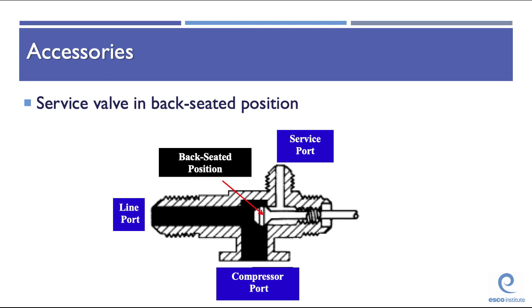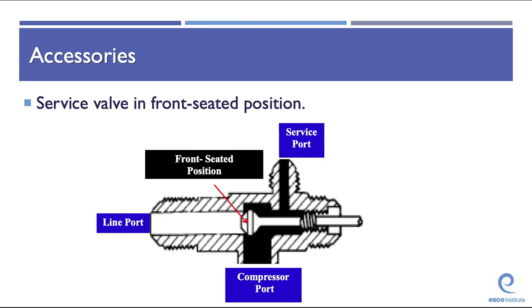You do not run equipment with the discharge valve, that's the high side off the compressor, ever in the front-seated position. You'll blow the compressor up.